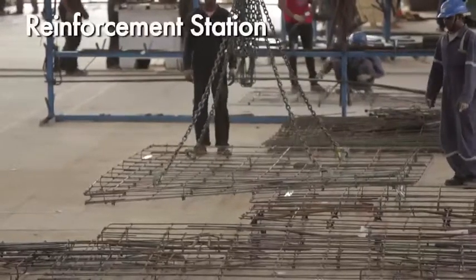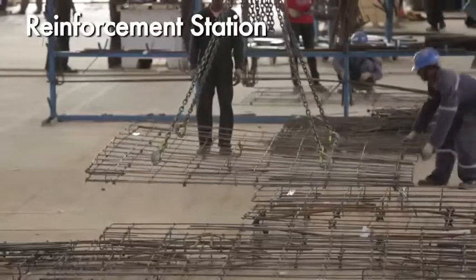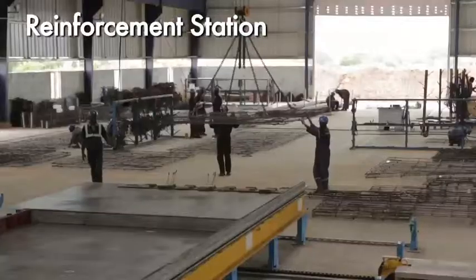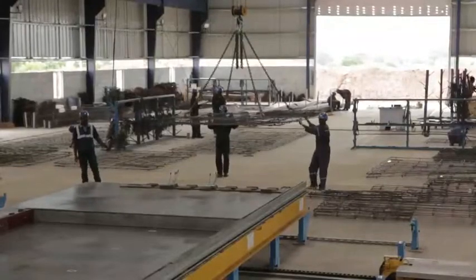Reinforcement station. The respective rebar cage is shifted through the EOT, electric overhead traveling crane, and placed. The station in charge has to check the correct cover for the rebar.